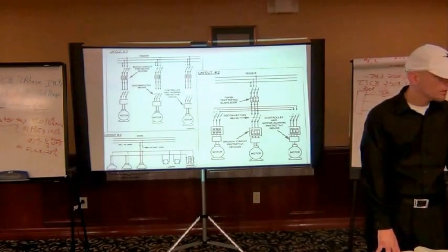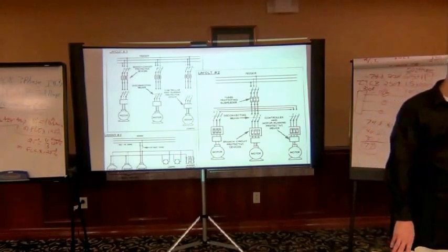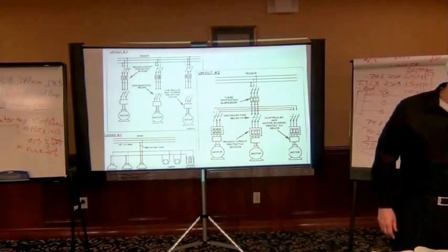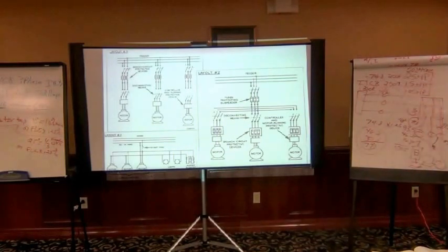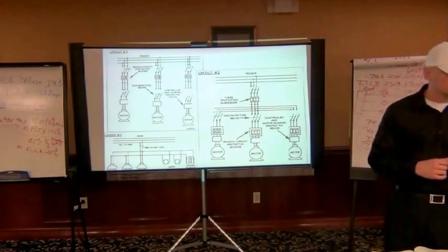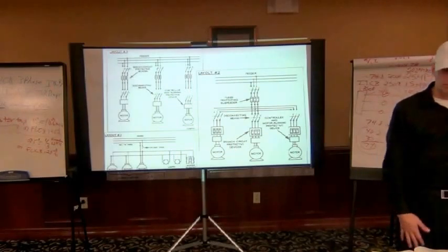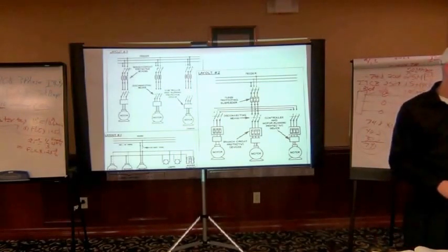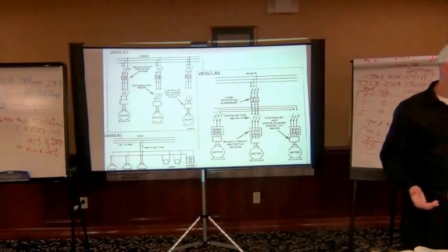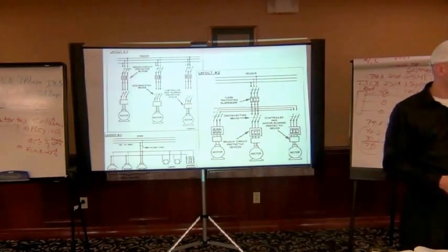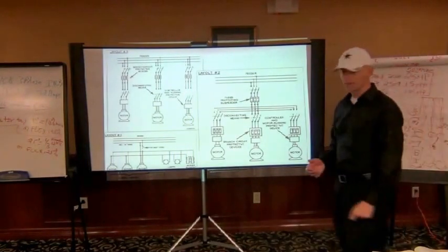50 horsepower. What size breaker for a fire pump motor? You catch what I'm saying here on this fire pump motor? It's a 50 horsepower, 480 volt, right there. 363. You have to carry indefinitely that 363, which means you're going to have to select a size larger than that 363. So they don't have 375, so it'd be a 400 amp breaker. In other words, you damn near want the fire pump motor to melt down before it shuts off. Only thing you don't want it to do is set fire on its own self, and that'd be kind of bad.